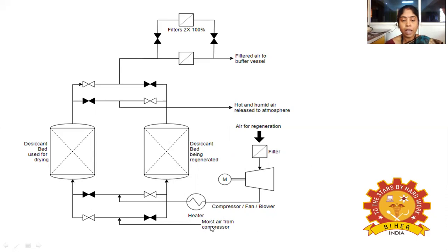Here in this case, we'll let the air in from the compressors, and this will be sterilized in the drying step. Once it has been sterilized and regenerated, it will be taken to the next filters for the next processes. This acts as an output that will be taken to the fermenter for any reactions to be carried out. See the symbol here; this is the filter.